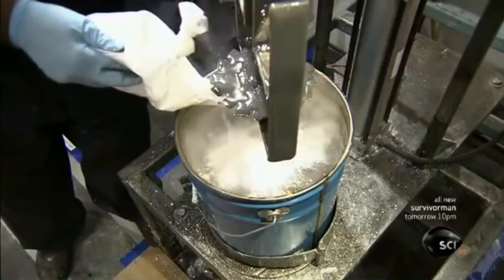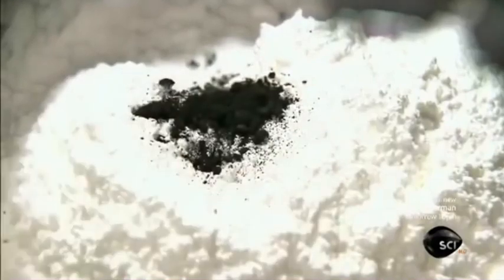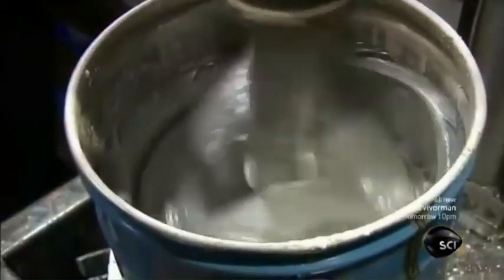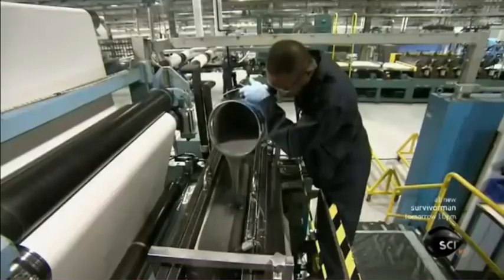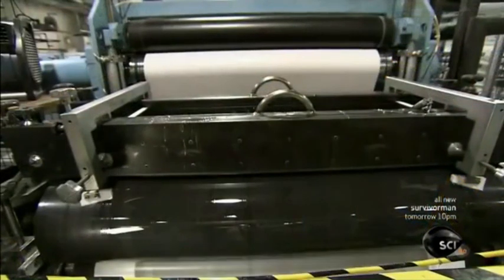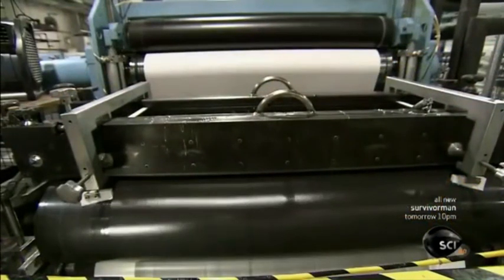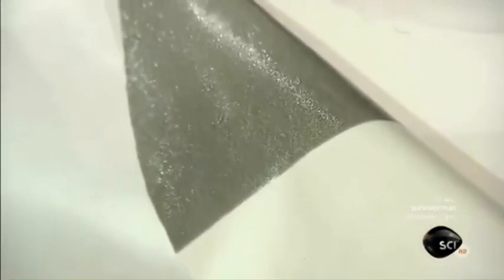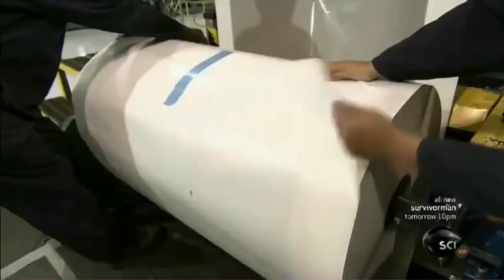Another form of carbon fiber is pre-preg, sheets of resin-impregnated carbon fiber ready for molding. It's like ready-to-bake cake mix. The resin is a formula of epoxy and various powdered hardeners and accelerators. Workers pour the resin into a filming machine, which spreads it in a thin, wet layer onto paper. The paper is pre-treated with a release agent to prevent the final product from sticking, like spraying a baking pan with non-stick coating.